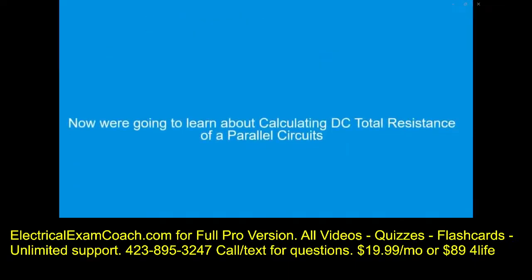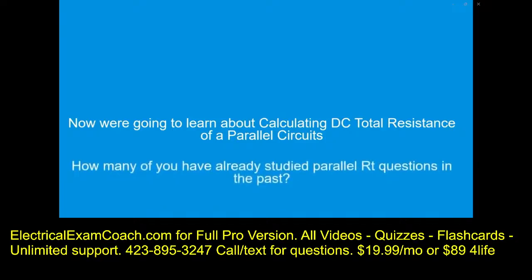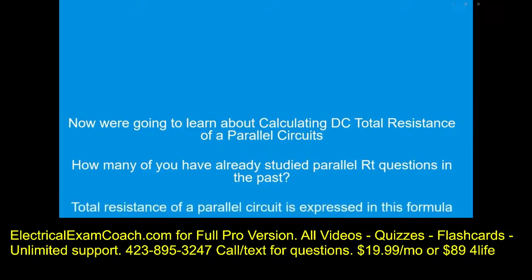Now we're going to learn about calculating DC total resistance of parallel circuits. We're also going to learn about calculating voltage drop across an individual resistor in a parallel circuit. How many of you have already studied parallel RT questions in the past? The total resistance of a parallel circuit is expressed in this formula.